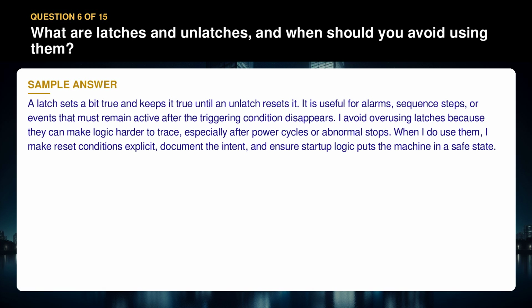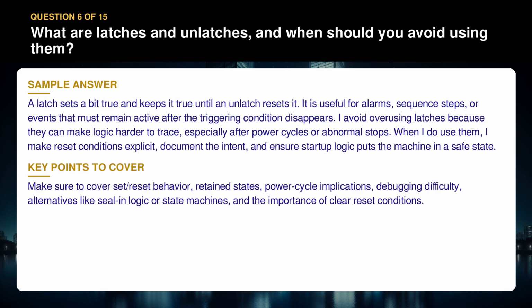When I do use them, I make reset conditions explicit, document the intent, and ensure startup logic puts the machine in a safe state. Make sure to cover set reset behavior, retained states, power cycle implications, debugging difficulty, alternatives like seal-in logic or state machines, and the importance of clear reset conditions.